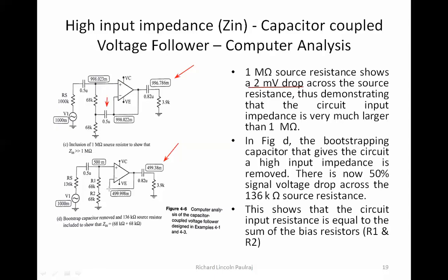So not only removing the capacitor, but then we have even decreased the capacitance. So as this capacitance decreases, my output voltage also will decrease. As this increases, okay, my output voltage increases. See here we had 1000K and the value is almost okay. So if I still increase the resistance here, it is going to be as ideal as input voltage, which means as equal as input voltage, right? So you're able to get something as to how the value of resistance can play an important role. What is the importance of this bootstrap capacitor, right? Yes or no, students?